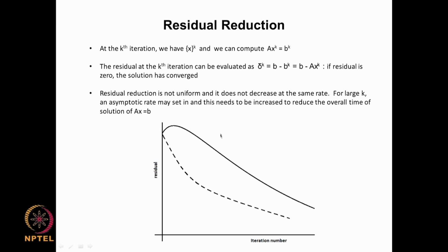So in this part there are different eigenvalues and all of them are contributing here, and sometimes they contribute in such a way that initially the error does not decrease, especially in practical CFD computations, but then it eventually starts decreasing, and as it gets closer to the solution it will be decreasing at a constant rate.